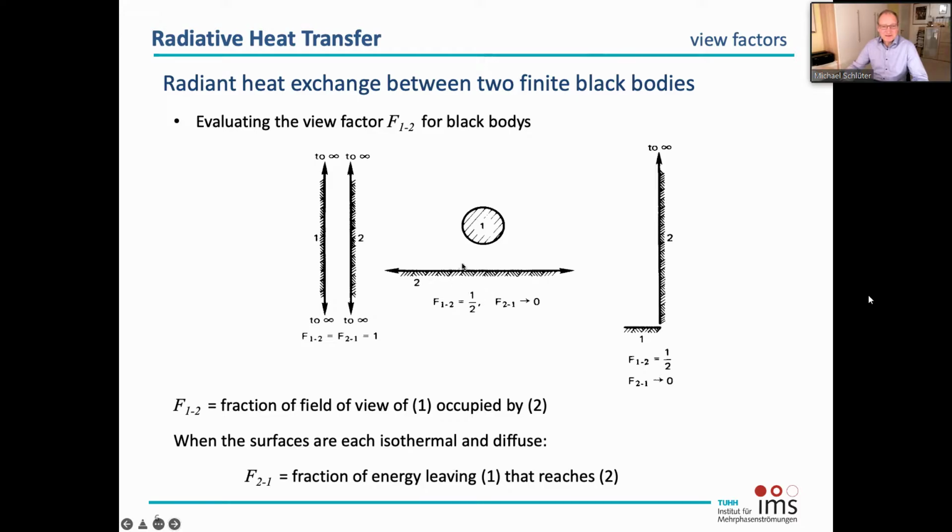And we distinguish here between two view factors. One view factor is from one surface. So this is here, for example, the view factor 1,2. It means we are sitting on this sphere here and we are watching the second surface. So how much radiation is caught by this body from the radiation that is emitted by this plate here.